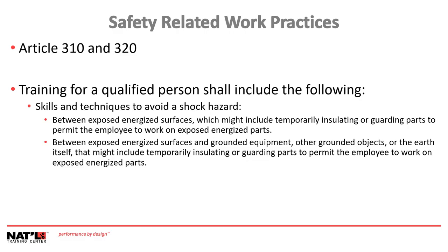Qualified persons shall be trained and knowledgeable in the operation of cell line working zone equipment and specific work methods and shall be trained to avoid the electrical hazards that are present. Such persons shall be familiar with the proper use of precautionary techniques and PPE.